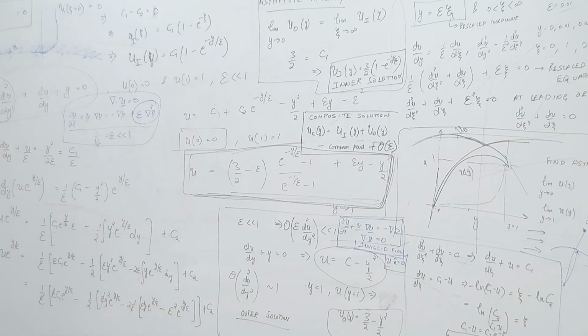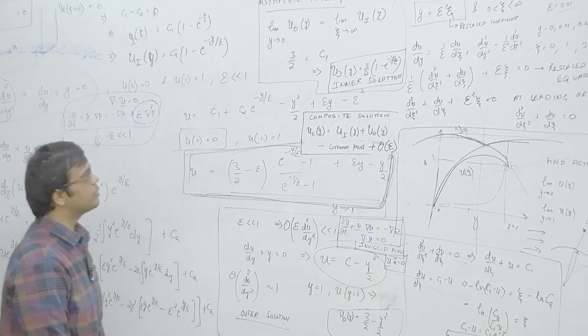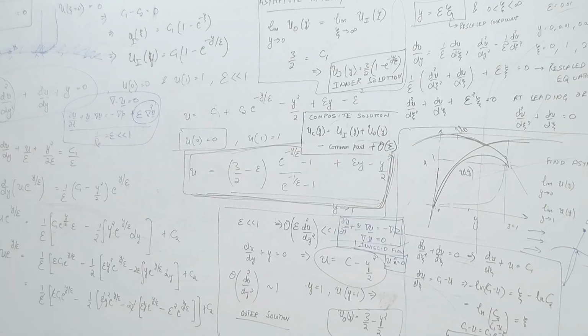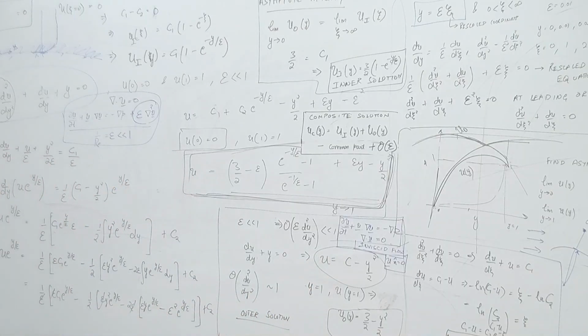It is from Panton's textbook, you can look at it, and there are further examples which we can discuss where asymptotic matching is used. But what I want you to understand is the motivation of looking at inviscid flows and boundary layer theory as two separate parts whenever we are looking at high Reynolds number flows.